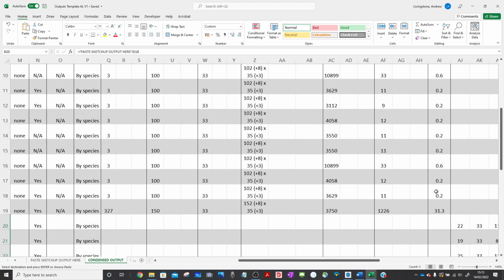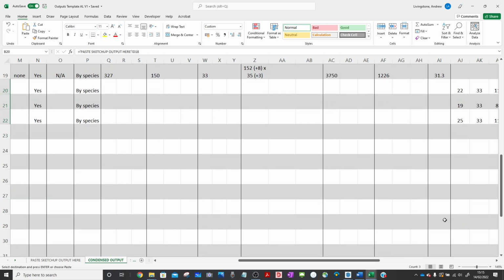And it would be a simple case of going to the very bottom and summing the whole lot, and that's the total amount of glue or the total amount of timber needed for that project. And if I happen to know my GWP or my embodied carbon properties, plonk that in, multiply it by the volume. It's as simple as that. So all you really need is the volume. You can do it in Excel afterwards. You can be a bit more fancy and do it in BIM. It's totally up to you.